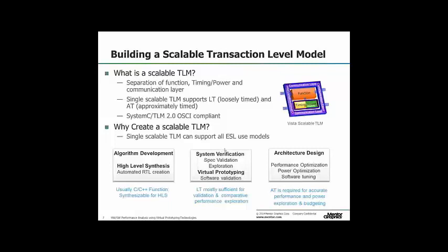There are many different use cases when we start to use a TLM environment in conjunction with SystemC. This ranges from doing pure performance analysis at a high level down to a fully functioning platform that you can run software on. There is a concept which we call scalable transaction level modeling, and this allows the functionality and the timing and power and the communication layers to be kept separate from one another.